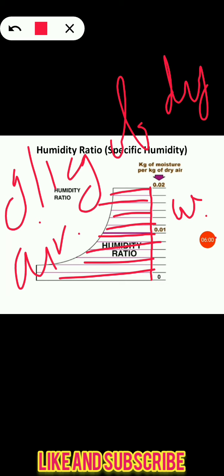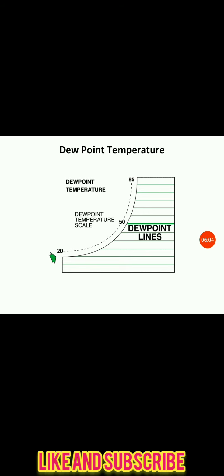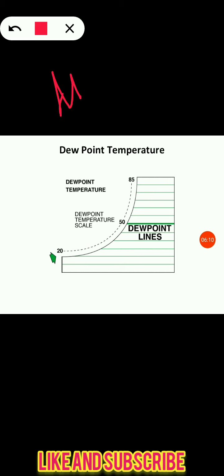The next psychrometric term that we have to know about is the dew point temperature. As I told you earlier, whenever we know the dry bulb temperature and wet bulb temperature of air, we can easily find out the dew point temperature. Suppose the condition of air is represented by this point, then if you draw a line leftwards, the point where it crosses the saturation curve gives us the dew point temperature.